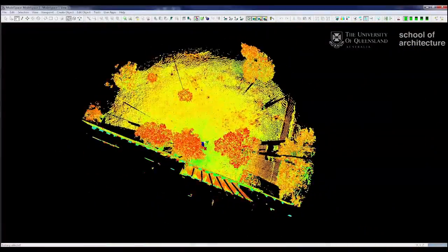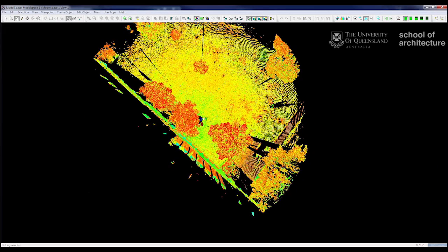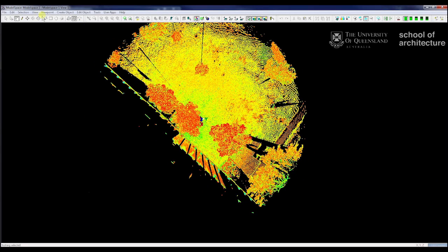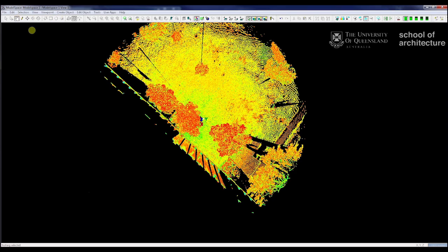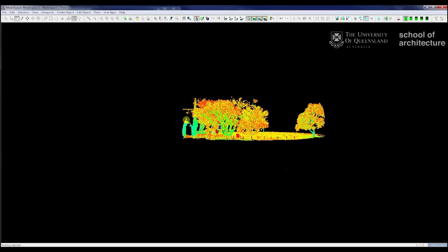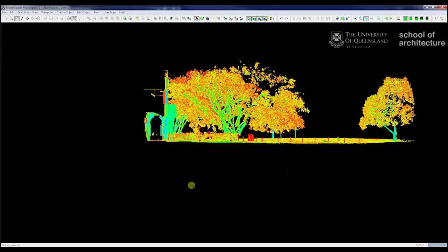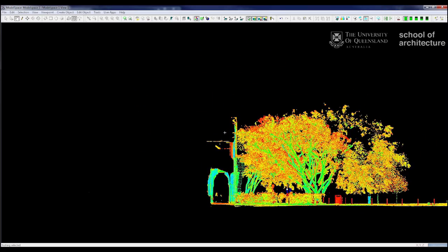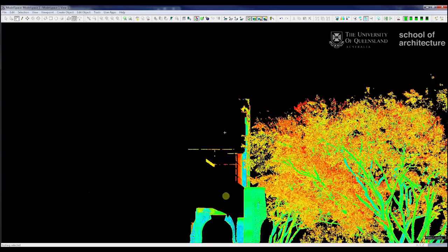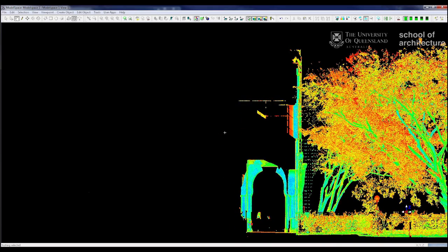Go here. This one doesn't have quite as much. We'll go into graphic. Select all the data that's out of here, essentially out of range. Like that. Select all. And close, just to make sure there's none through here. We've got some nice clean lines there, so we know where this wall is, so we can select all the data that is behind this wall. We know that's none of that we want.